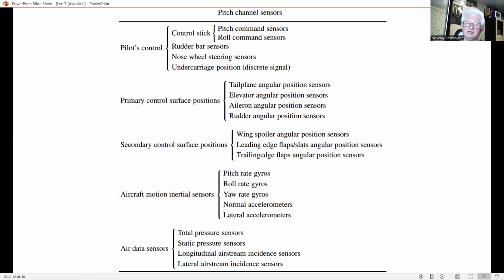A first-order list of sensors for a typical system is set out in this table to show the numbers of sensors involved in these respective tasks. Most of these sensors would be at quadruplex or triplex level redundancy. Cross-lane data transfer: data transfer between the individual computing lanes to enable cross-comparison of output.